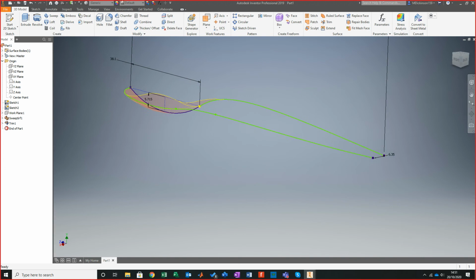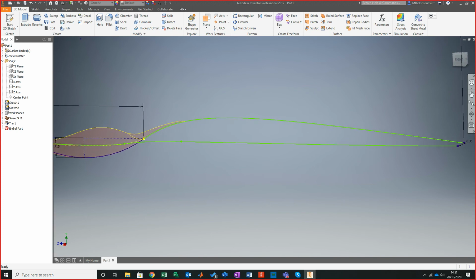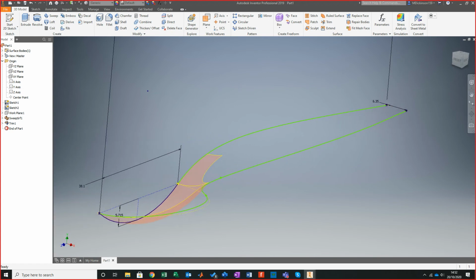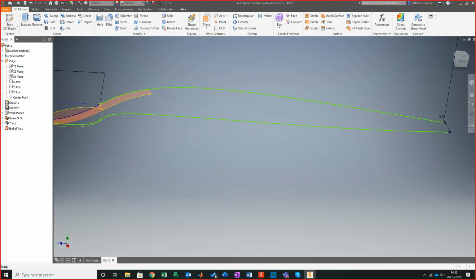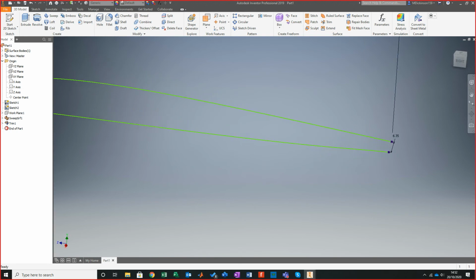Now, what I've done with this is I've made this a flat end spoon. Remember at the beginning where we had this spline, I can push it upwards if I want to give it more of a rise on the back, to put more of a profile into there, or not. In fact, we'll do that in just a second, but this is going to allow us to get that profile in position. So the next thing I now really want is a plane to sit interface on these two. Now because they're horizontal, it should allow me to do that, no problem.